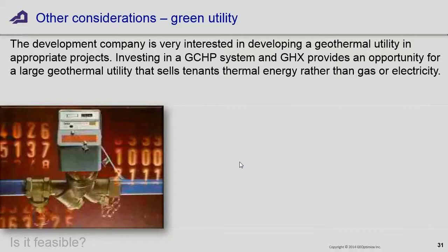You can get heat pumps that will produce water up to about 150, 160 degrees Fahrenheit. They're not terribly efficient at those temperatures. Ball State University, I think, is running at about 140 or 150 degrees. They've got two central plants, and they're distributing hot and chilled water. Another way, the system done north of Vancouver on the district system, we're not heating the water with it.